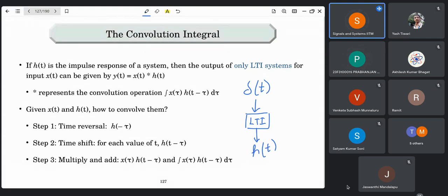Okay, so basically it is a function of functions. Let's say there is some arbitrary system. We don't know what that system is. You feed in some arbitrary x of t, and it produces some y of t. So basically it takes a signal and transforms it to some other signal. In that same fashion, it can take in a Dirac delta function, which is a signal, and transform it to some other signal. And the transformation that it produces is what we call the impulse response. I don't know if that answers your question, or maybe if you rephrase your question more clearly, I can address it.